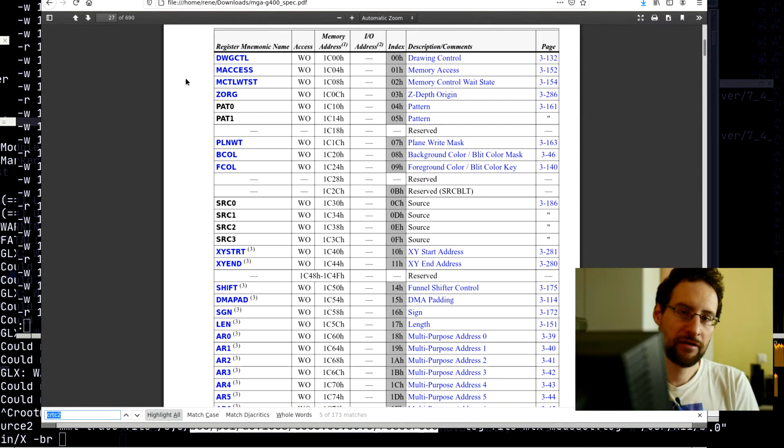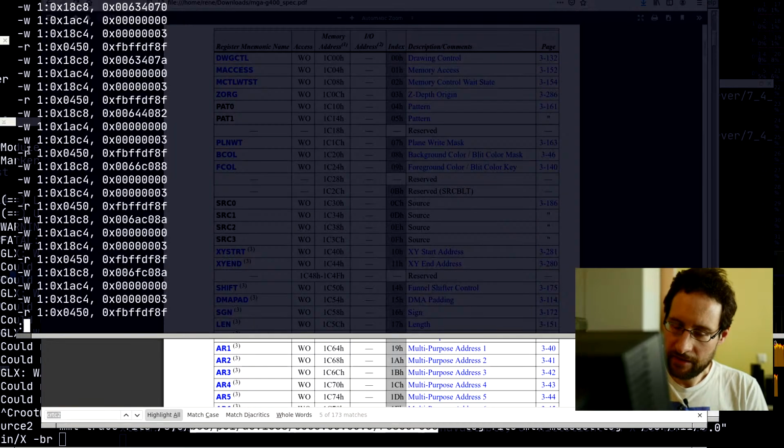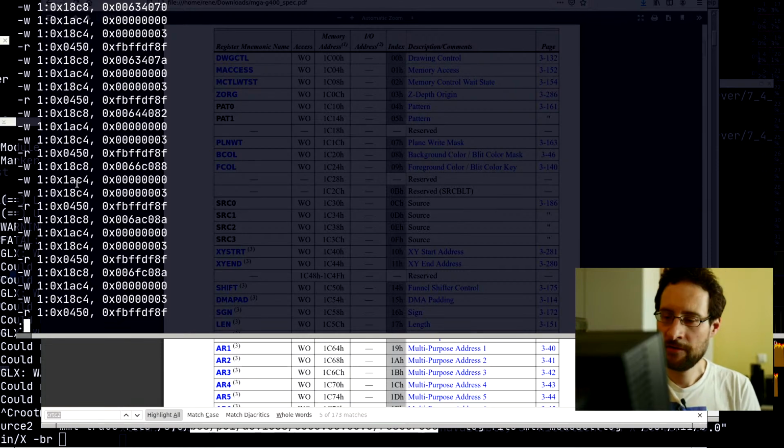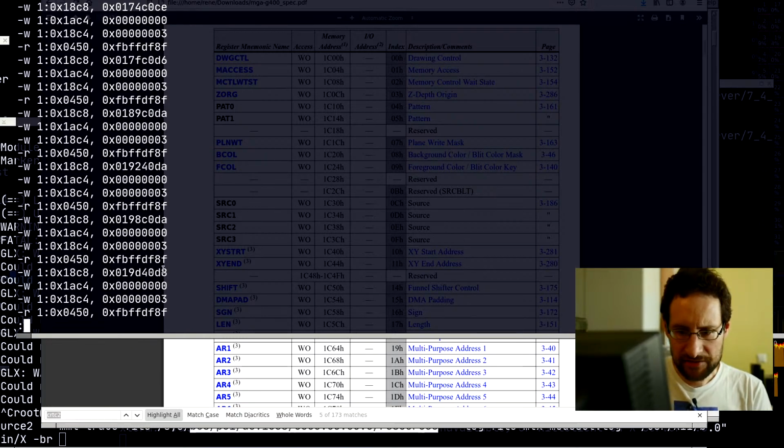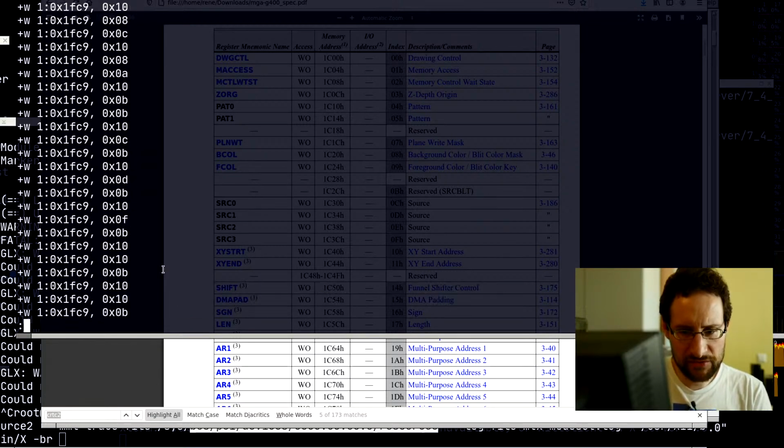In some cases where no open source was ever done before, like the Imagine 128 or the Lynx 3D. Only for the 3dfx Voodoo have we done the mode setting, and for that you can watch the 3dfx Voodoo video. So we would need to program all the PLL, the phase locked loop, all the video mode parameters like front and back porch, and all the timing parameters. And yeah, this is unfortunately the time-consuming stuff of reverse engineering, making sense of these numbers.